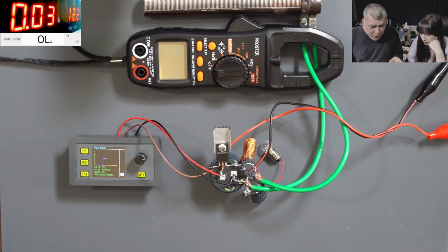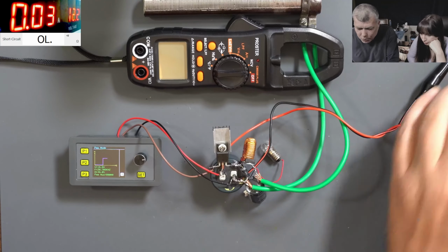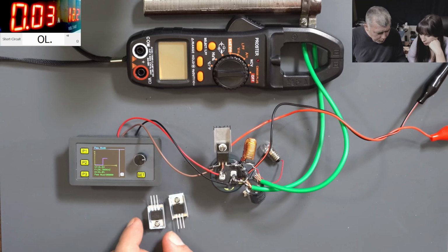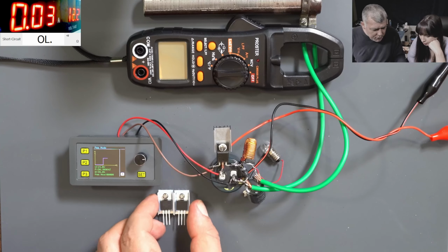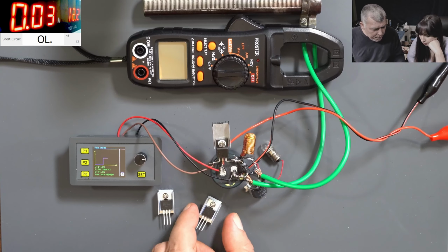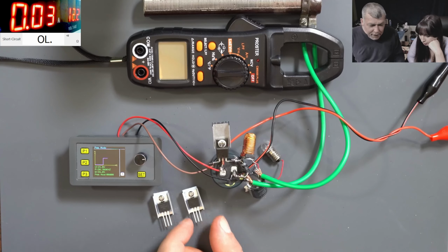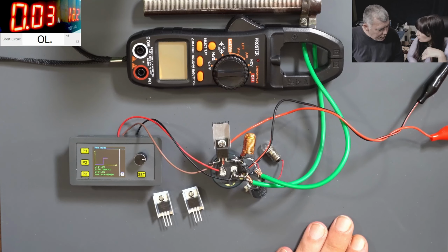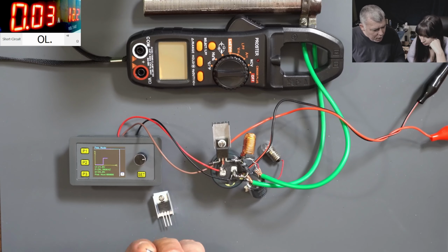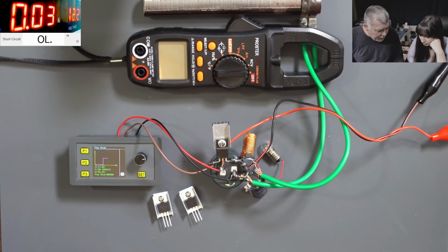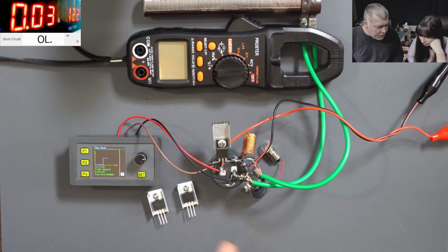So what do I want to change from this? It's not because of the power. We have here two MOSFETs. I bought them from eBay. Now, this is like a 10 amps MOSFET, I believe, 10 or 20, I don't remember. Those are 100 amps each. And we don't need 100 amps, but the internal resistance is 0.00 something, which means close to zero. That means less heat, because we don't have big heat sinks. So that was the idea why I bought the MOSFET. We don't need that kind of amps, but we need less heat on the heat sink.